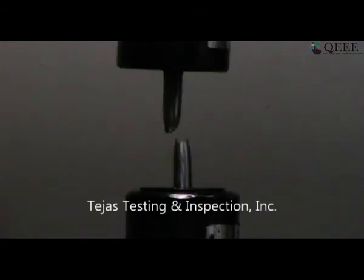Okay, now you see the difference, and if you appreciate and understand the difference, many of the concepts in design will be clear. The first one was a compressive test on a brittle material, where you increase the load and it fails suddenly, and before it fails, it hardly gives any sign. Whereas in a ductile material like steel, when it is subjected to a tensile test, before it fails, it gives you some warning. In this case, the warning is in terms of localization of deformation.